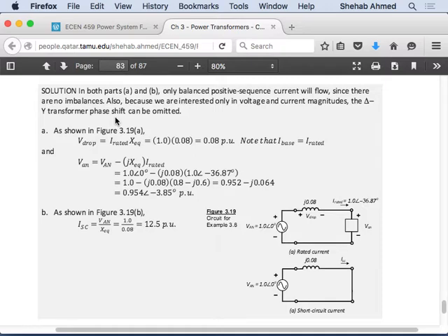But here I'm just asking for magnitudes. Yeah, don't ignore transformer phase shift. That's like the previous problem. You have to consider the phase shift, and you have to keep thinking star, delta, delta. You have to make sure you take that into account. If I say ignore transformer phase shift, the equivalent circuit in per unit will be a short circuit with an impedance in series. That's it. Which is what we have here. Just a short circuit. There's no transformer, right? So it's just a short circuit.